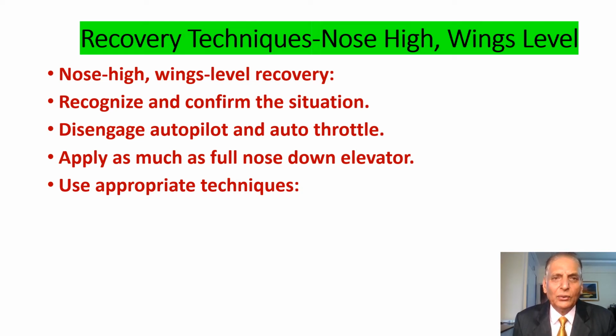Nose high wing level recovery. To summarize, recognize and confirm the situation, disengage autopilot and auto throttle, apply as much as full nose down elevator, use appropriate techniques.